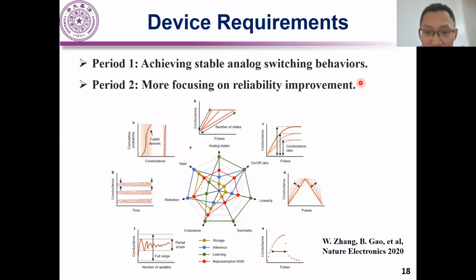So you mean this linearity? We need to optimize this linearity. Yes. So this is a typical weight update curve for measuring the analog RRAM device. To measure this curve, we just apply the identical pulse, and the conductance will change pulse by pulse.